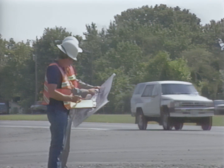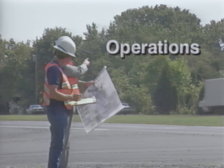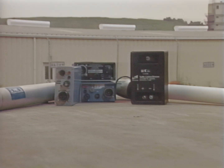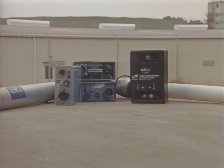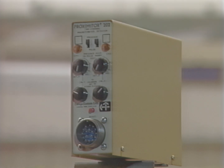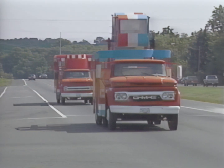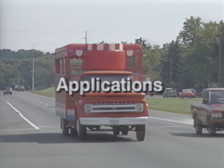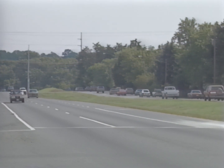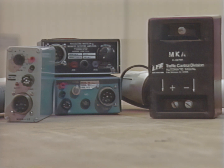When choosing a detector based on its operational characteristics, consider its weak points as well as its strong points. For example, magnetic detectors, capable of passage detection only, are inappropriate for operations requiring presence detection. And magnetometers cannot be used with NEMA controllers in situations requiring a delayed call capability, a feature they do not possess. When selecting a detector based on applications, choose a loop detector or a magnetometer for detecting a large area and a magnetic detector for a small area.